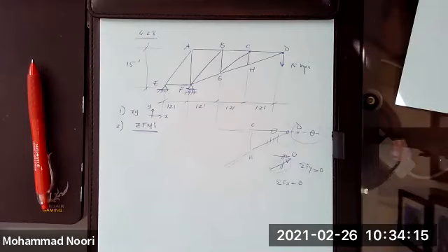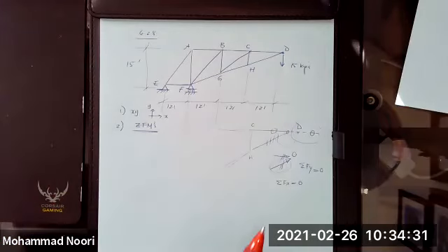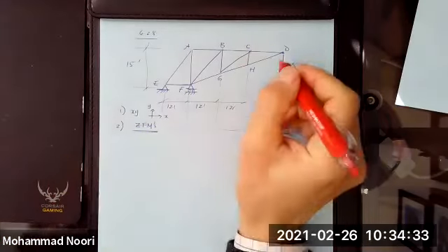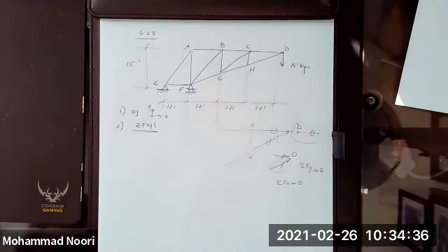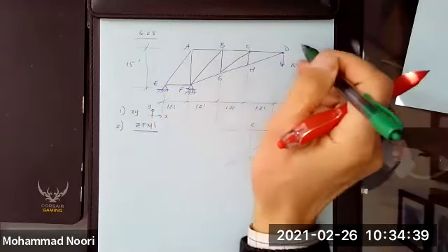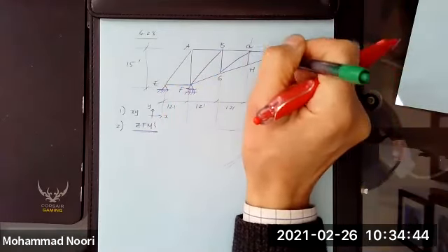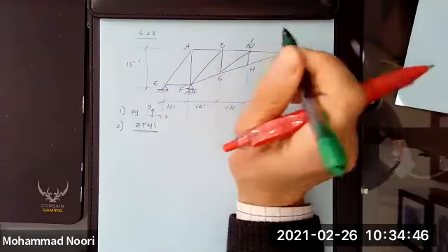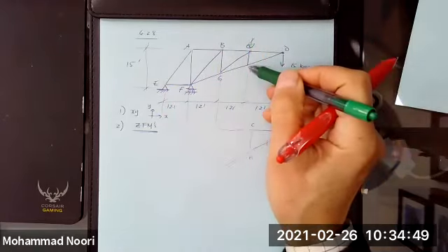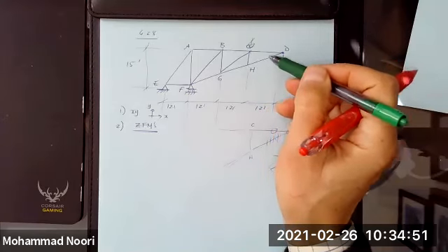This is a concept which is very important, and I've given many exam problems trying to help you to remember that concept. So we don't have that here. Let's go on with identifying the zero force members given this loading. So in this truss, if the loading was here instead of here, these two would be zero. Okay, remember that. All right, so let's go with joints with three forces coming together and two are collinear.